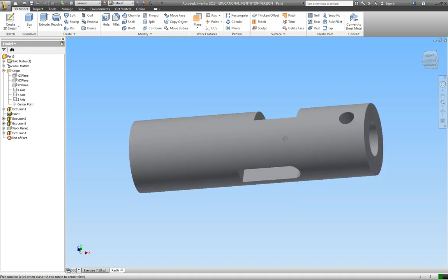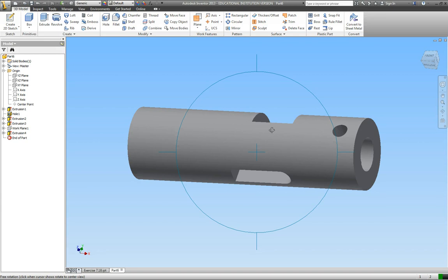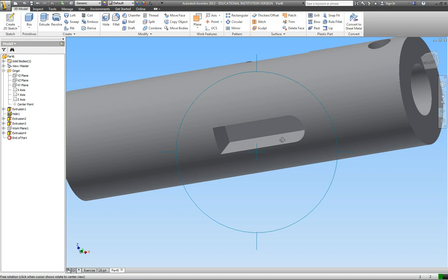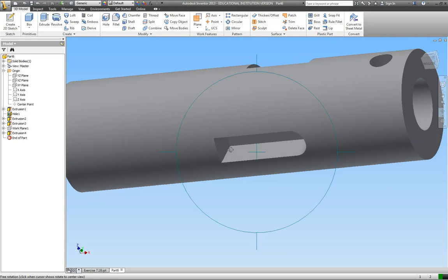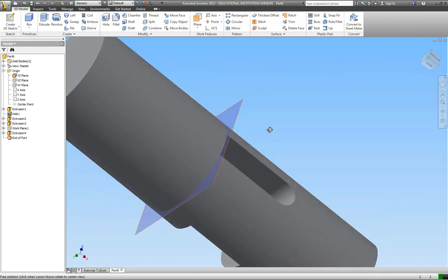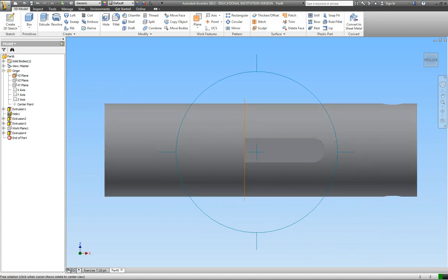Now early on in our very first extrusion, we did an asymmetric extrusion. I really wasn't thinking about cutting this object out. I could have actually used this as a sketch plane. I didn't think about that in advance. But just to show you, the YZ plane that we placed at the beginning, by the way we did our extrusion, passes through that surface that we just created, as it should.